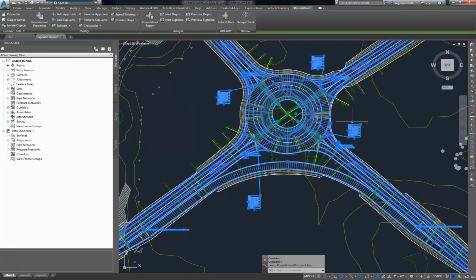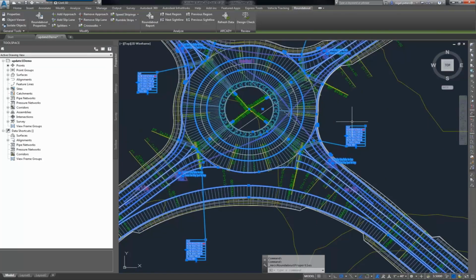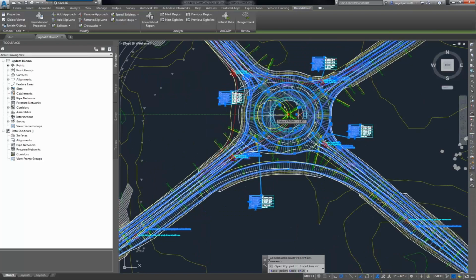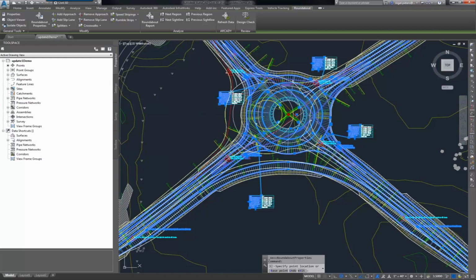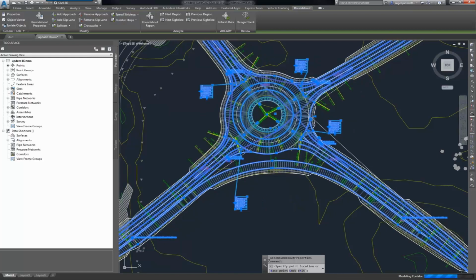So when you create a roundabout, this roundabout, again, performance-wise, if you move the center of the roundabout, it will within seconds rebuild the entire corridor, recalculate the elevations, the crossfalls. We support an overall tilted plane for the center of the roundabout. We support 2 crown lines on the roundel. We support slip lanes. Any arm can have a slip lane. We support pedestrian crossings or crosswalks, currently not on slip lanes but on individual arms. The roundabout has visibility reports, fastest line reports are calculated, and swept paths can be driven, and vehicles automatically drive around the roundabout.